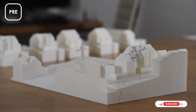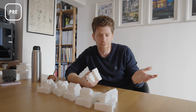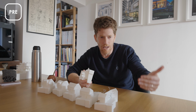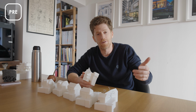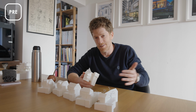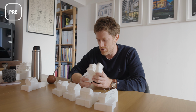I also find that my volume becomes massive, especially when I set it in its urban environment, in the overall model. I see that my roof is just coming too high, and that's a consequence of following the guidelines, unfortunately. I can build up to 12 meters deep, my main volume, and since I have a more or less 45-degree angled roof, the total height of my roof will be an additional 6 meters. That's quite massive.